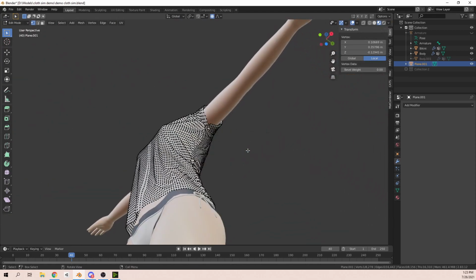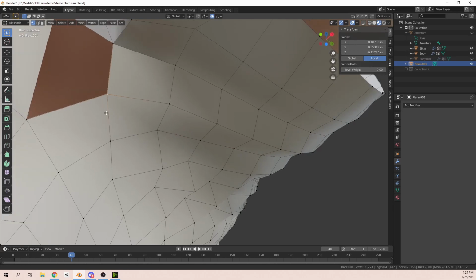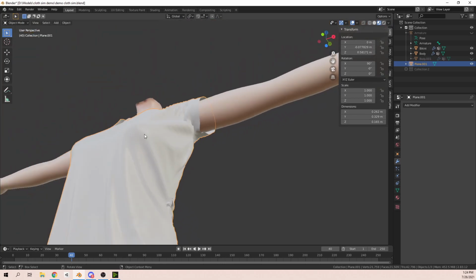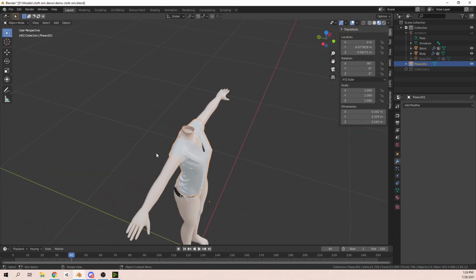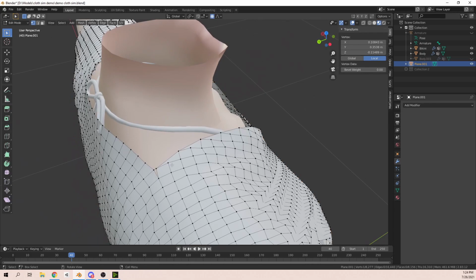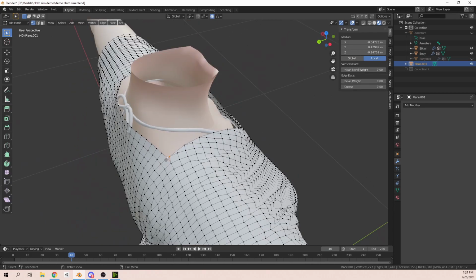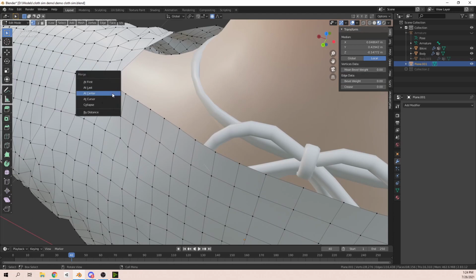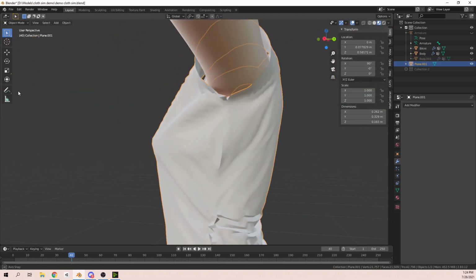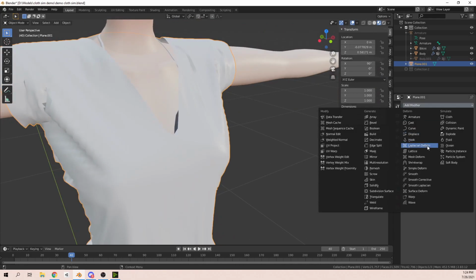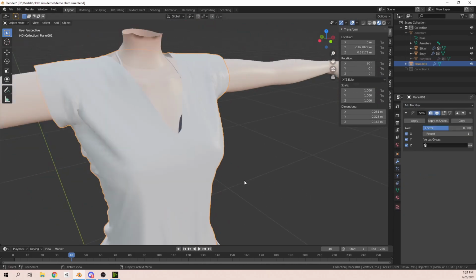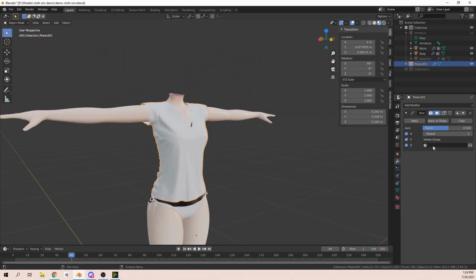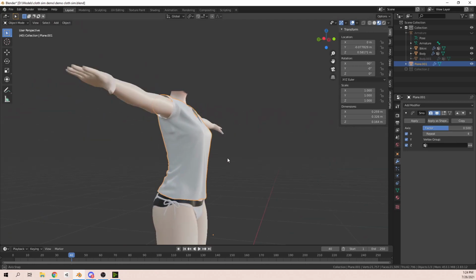Same as there. View selected. I'm pressing the tilde key, which is the one on the left of one. Do that. So it's still lumpy. We can fix that. Merge that there. Merge that there. And I don't think I had a problem. No. So I'm going to add a smooth modifier. I'm actually going to make it like 3 or 4. For this case, I'll make it 4.